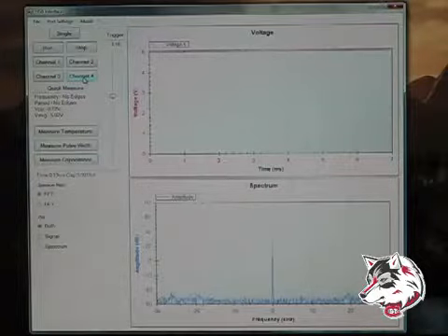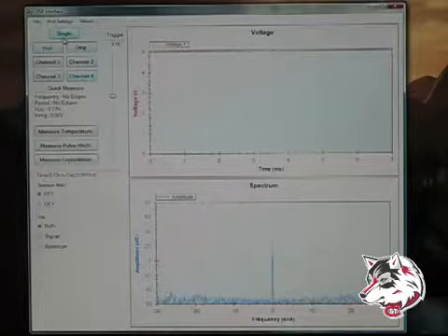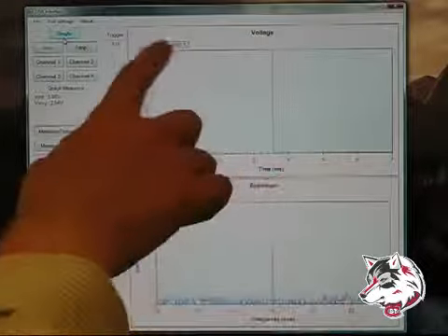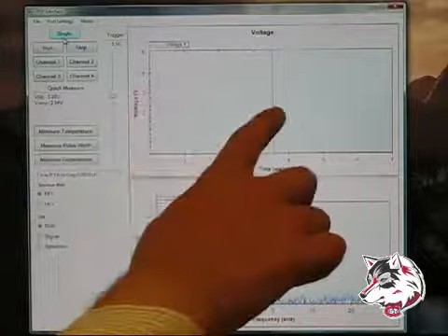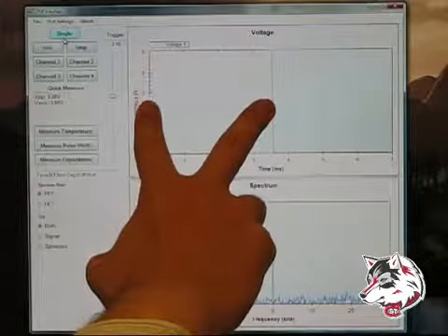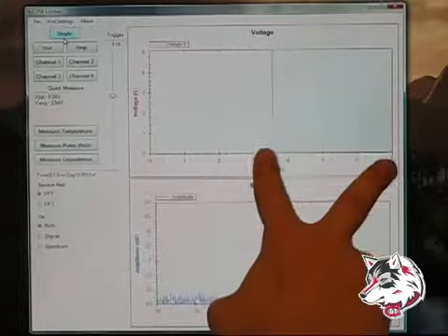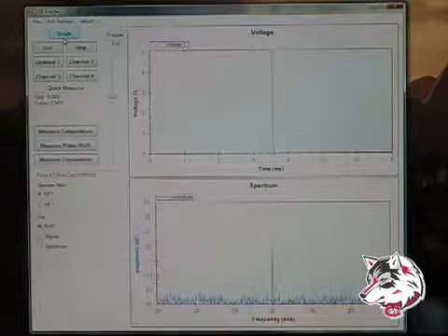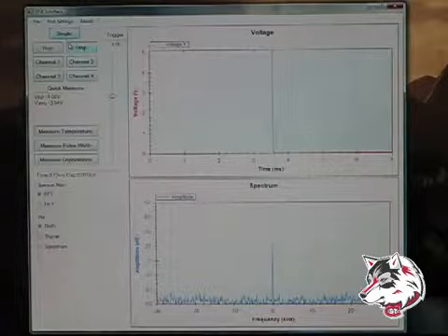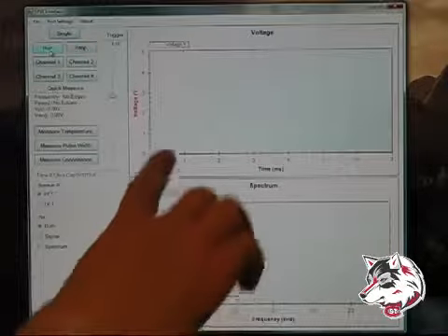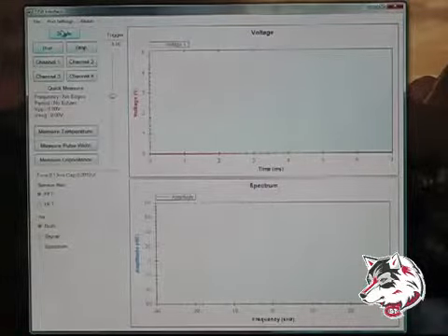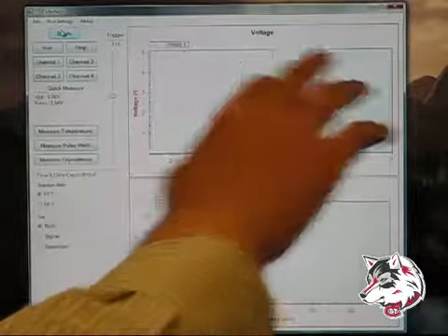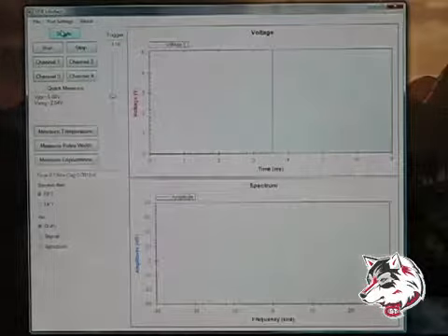So if we wanted to do a single capture, we can leave it high, click on single, and as soon as I click the button, boop, sees right there the voltage drop. Once it crosses this trigger, it keeps the previous 256 values, and sends the newest 256 values. So the total sample is 512 8-bit values. And we can do the same from high to low. So right now we're low, so we can click on single and let go of it, and you can see it captures that rising edge, and then waits for it to come.